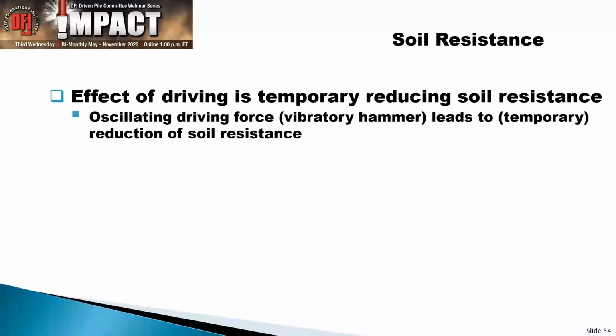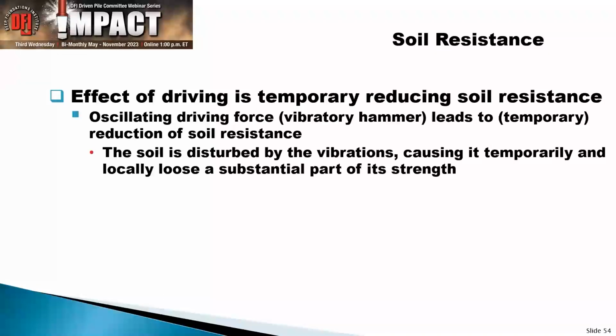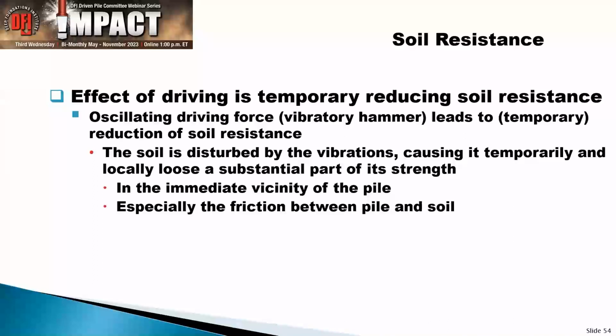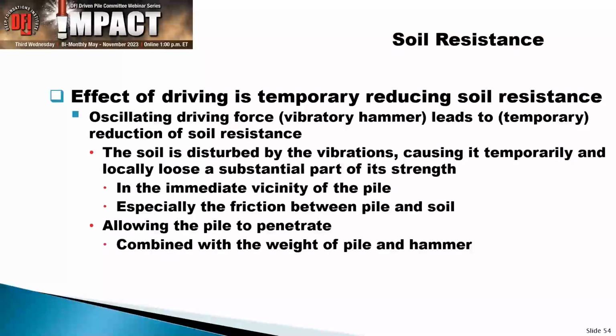So what did we do? With vibratory driving, you have a temporary reduction of the soil resistance, and that is in the immediate vicinity of the pile. Obviously, the main thing is the shaft friction, that's completely gone. You allow the pile to penetrate, and that penetration is then also a combination of the weight of the pile and the hammer.